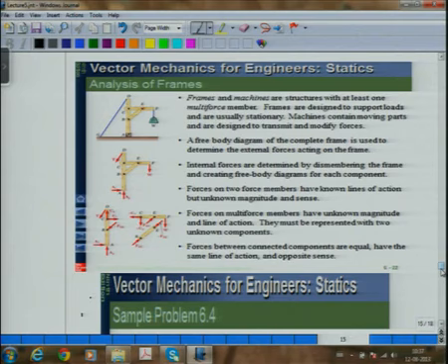So here, if I take moments about A equal to 0, I will get T. I do sigma Fx equal to 0, sigma Fy equal to 0, and I will be able to get Ax and Ay. Next, suppose I have to find the forces in each of these members at each of the pins. Then I start doing an analysis of the frame.